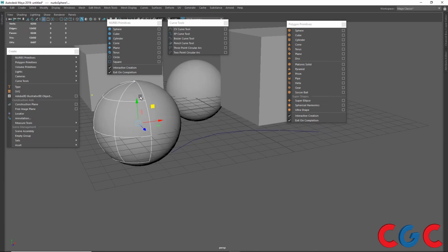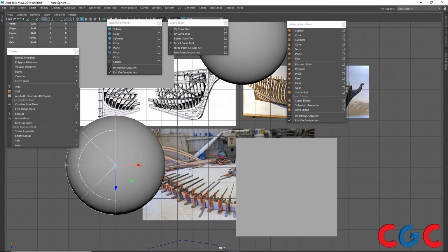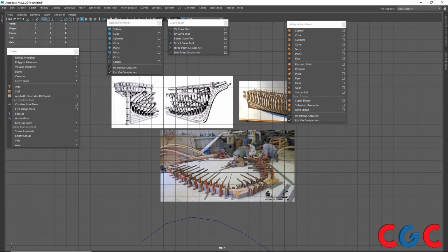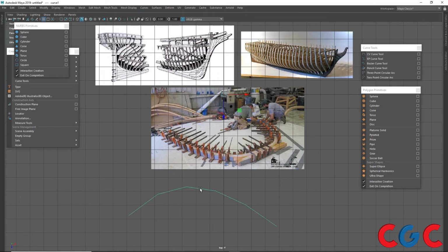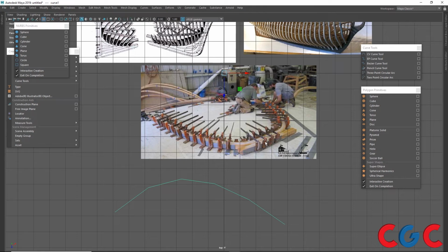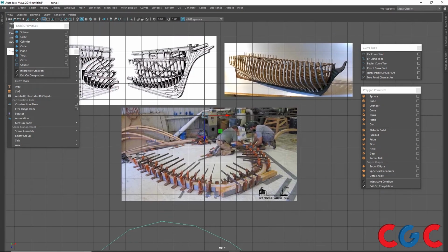First, we will see what this hull is and what a control vertex is. When I press space bar, right click, I will go to top view. In the top view, I have some images. I'll just delete these things. Now I have some images over here. Here I have the curve. So when I have the curve, you can see these curved wooden planks. The curve is obtained by applying weight or holding them. So this is how a ship's hull looked, something like a skeleton of a ship.